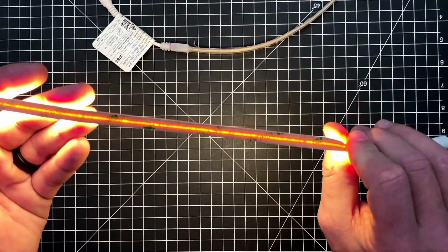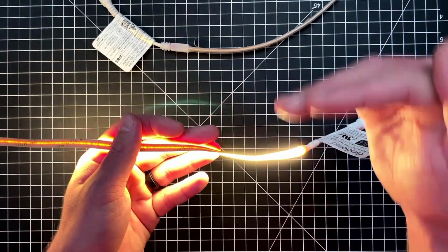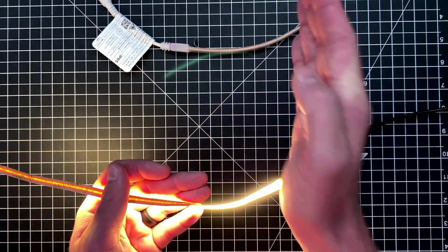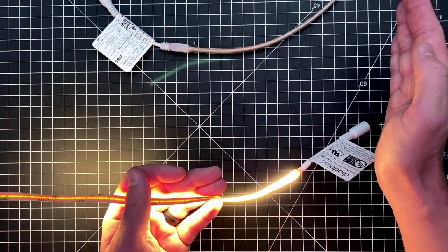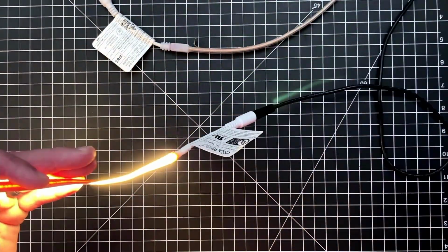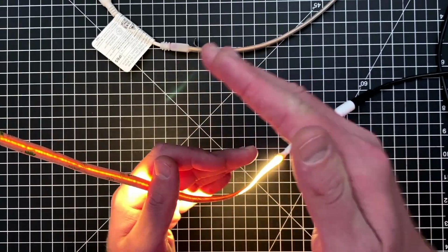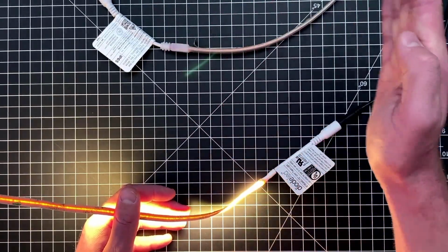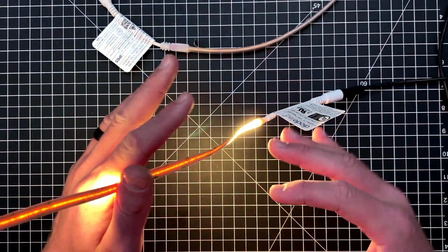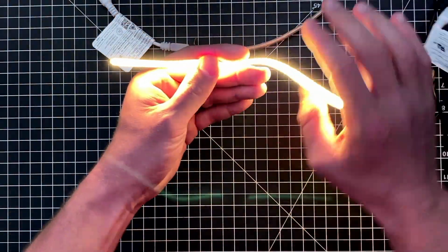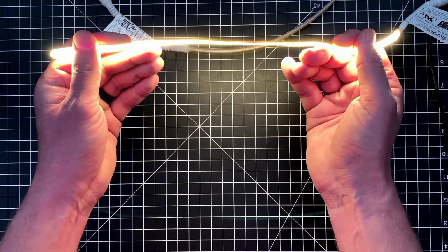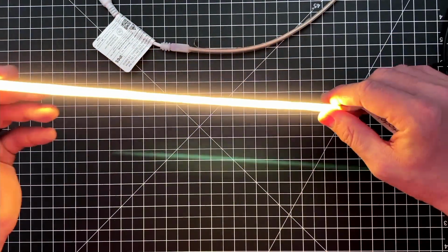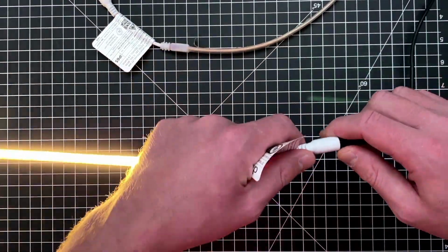The issue with that is being able to expand that product into anything with color changing. When you don't have individual diodes to be able to address, the color mixing is absolutely atrocious, right? It does not color mix very well. You can't create scenes that well. Anytime you're switching from color to color, it has very weird striations and variations. So this is why we wanted to go a different route. And instead of doing COB, we decided to do individual diodes across the entire PCB. And I'll explain in a second why that matters with tunable white and RGBW.